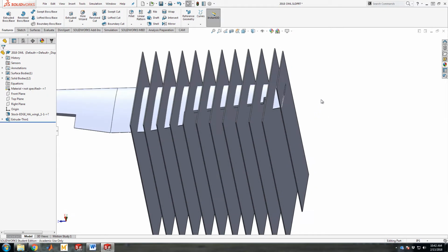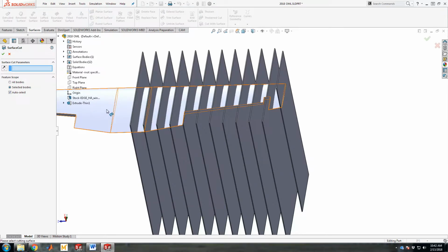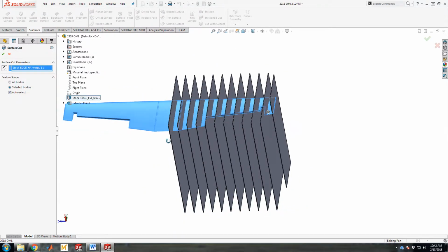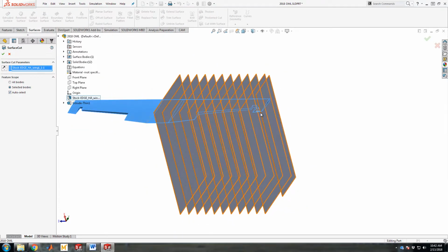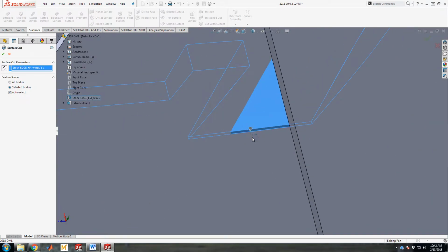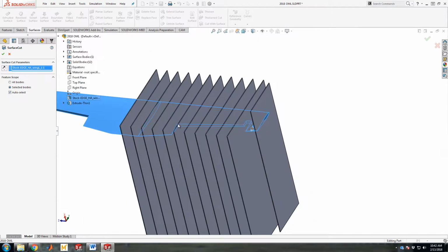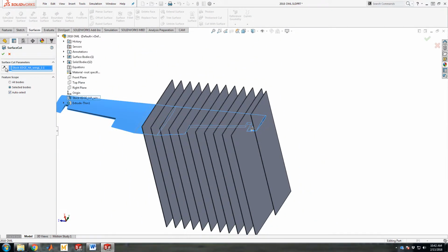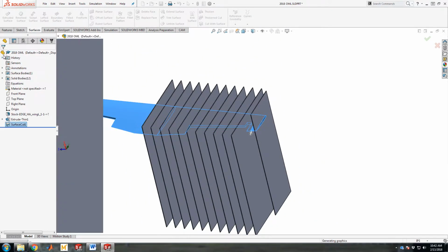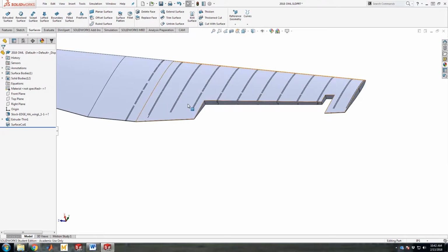Now to give you a preview of the magical step we'll do when everything is put together, we'll go to Surfaces, do Cut with Surface, select the surface that's going to be the knife cutting things. We look for the arrow, which in this example exists here. It's going to remove material on the side the arrow is pointing. So right now it'll remove all of the solid material on the inside of the wing. We'll flip that arrow, click OK, hope it all works out. In this case it did.